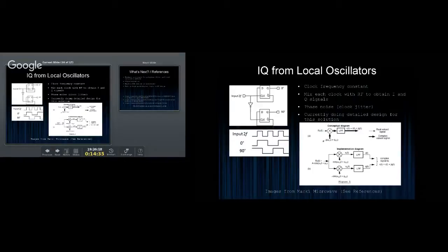actually I came across this, and it should have twigged a lot sooner when I was staring at a few of the digitized radio systems, because this is how they pretty much all do it. You can generate quadrature in the clocks rather than having to modify the signal directly. You modify the clock that you use to down convert in the superheterodyne architecture. And you can do that really conveniently using very high speed logic, which is convenient again, because most of us know that RF electronics can be a little bit picky at the best of times.